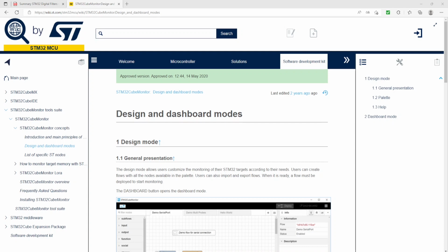We're gonna basically generate a connection between a Cube Monitor application in order to read some information from a spreadsheet, retrieve this information, send this information to some specific variables in our projects, process those variables using, for example, filter concepts, filter tasks, and generate output signal to some variables. These variables will be connected in the Cube Monitor project to an output generated CSV file.